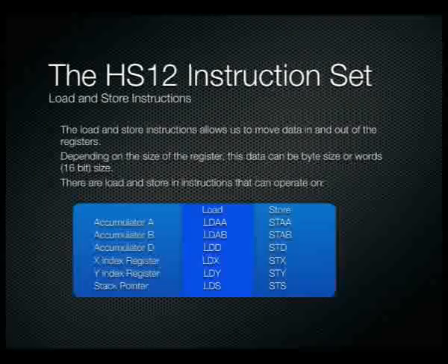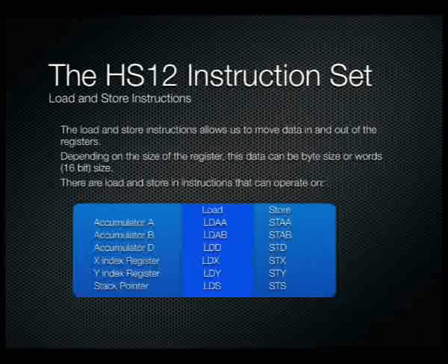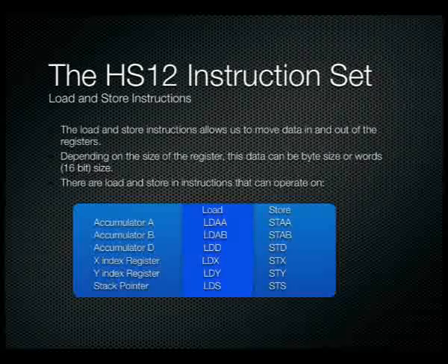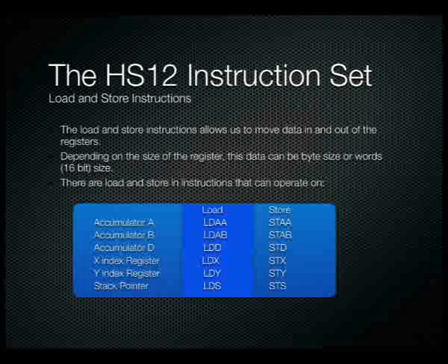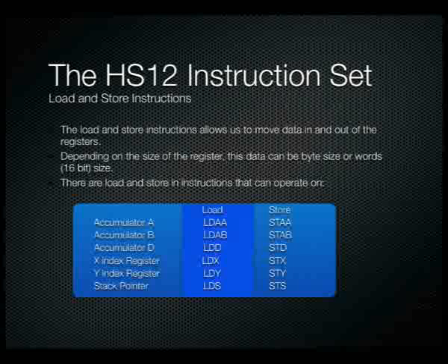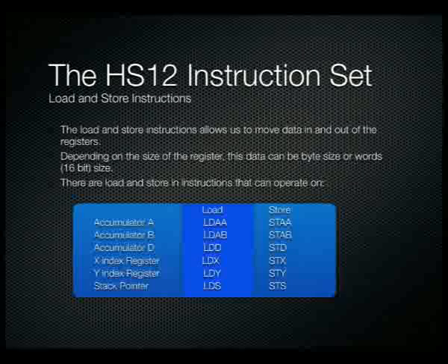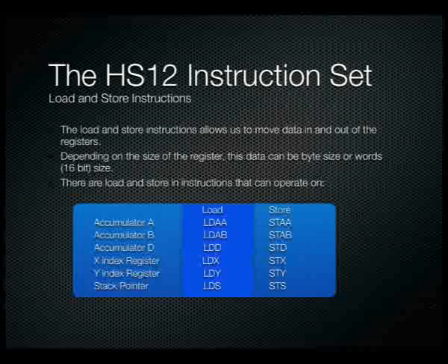So the accumulator D, the index registers, and the stack pointer are all 16-bit registers. They don't have an A in their name because they're 16-bit. And of course, when it comes to storing those values out of those registers, we have the store command. The ST in the mnemonic stands for store, and the naming convention for the registers is the same as it was with the load. So store accumulator A is STAA, accumulator B is STAB, and so forth.